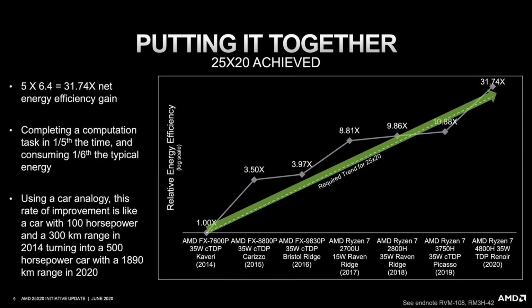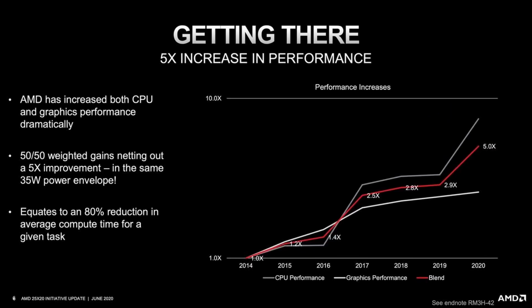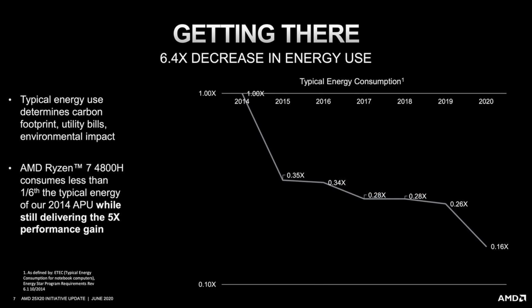To incredibly oversimplify this challenge, there are 2 main ways how AMD got around doing this. 1. Increase the compute performance for a given power budget through architectural innovation of their CPUs and GPUs integrated into the APUs. 2. Decrease the power use for a given compute performance by innovations in real-time power management and silicon-level power optimizations. A first stepping stone in that direction was the introduction of voltage adaptive operation and adaptive voltage frequency scaling technologies in Carrizo.